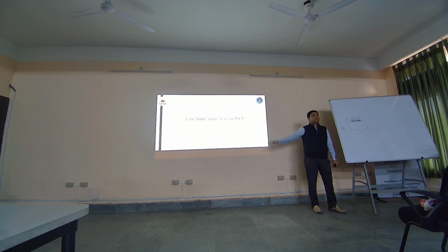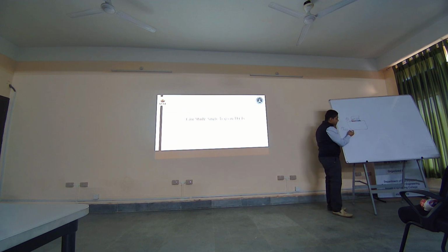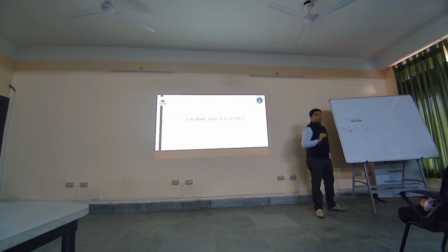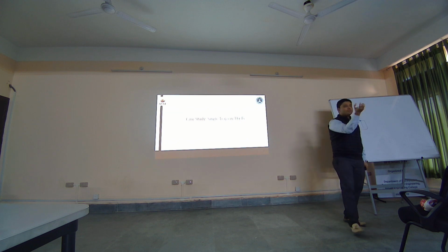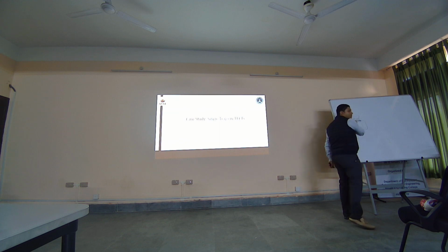which we are going to see a few examples of, and from here we are also going to see an application. Why are single traps important? Because suppose we are talking about TFETs, which we did a few minutes back, you know that your junctions are very, very important, right? Because here you have your on-state barrier and here you have your ambipolar barrier. Now, when you are defining your traps uniformly throughout your interface, you don't know which part of your interface is responsible for which dominant mechanism because your traps are spread throughout, right?